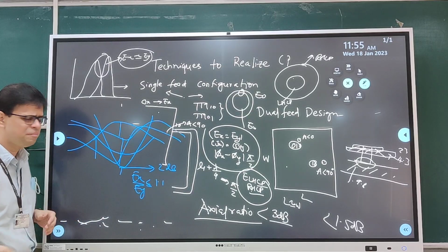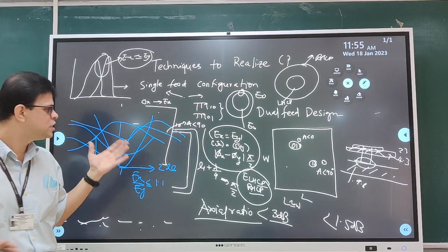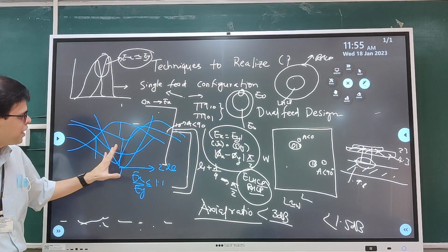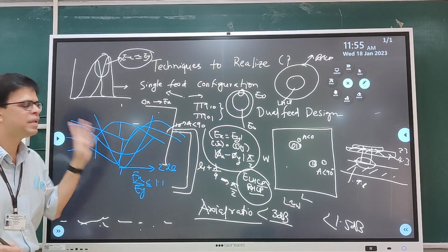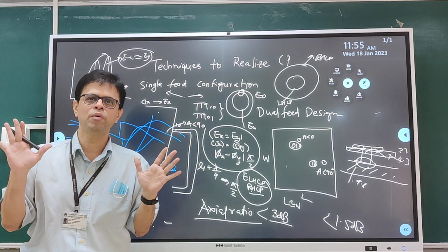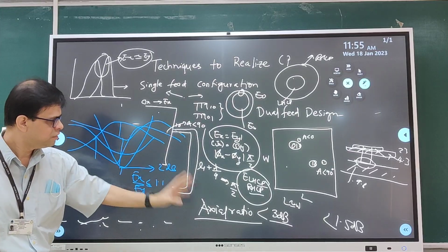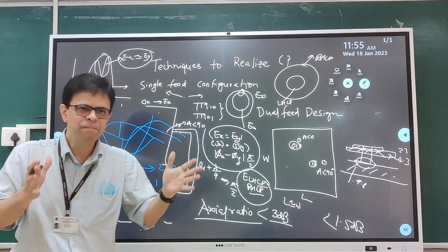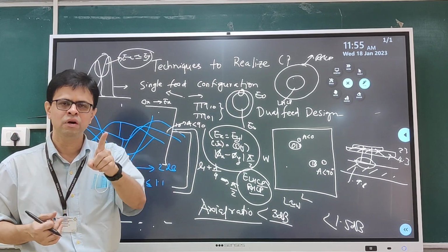You can generate these orthogonal field plots and their phase component using simulation software. CST does give that. Then try to plot and correlate where the axial ratio point is coming, and where the difference in the phase as well as the amplitude ratio plot is coming equal to unity. All these put together give me a limit that CP may not be the case that axial ratio or Ex by Ey is equal to 1 all the time.